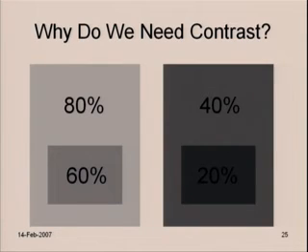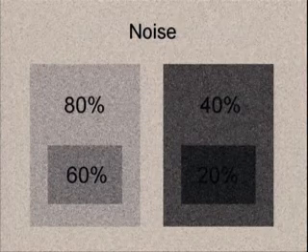So I'm not sure if I judged this right. So the idea is that you can read most of these numbers, but not all of them. Basically, you have 80, 60, 40, and 20% contrast. 20% contrast seems like you can at least see the lines okay. So why do you need more than that? Why wouldn't we accept lenses with 20% MTF? And the answer is noise.